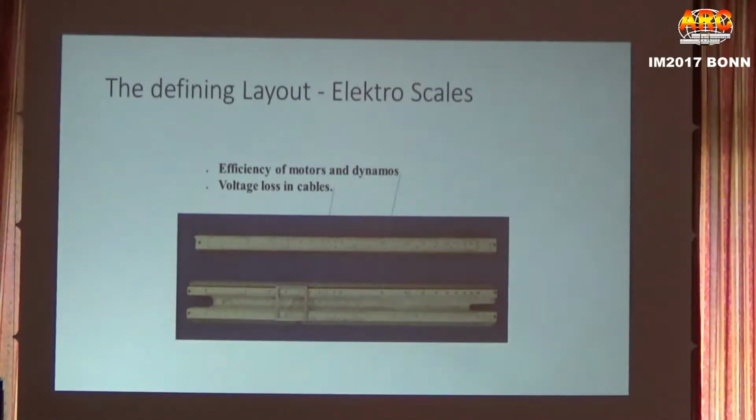So 850 over 1,000 gives you a power factor of 0.85. Now with a P scale, you just put 0.85 on the C scale and read directly off the P scale about, I don't know, 59.6, I think, which would have been the reactive volt amps.